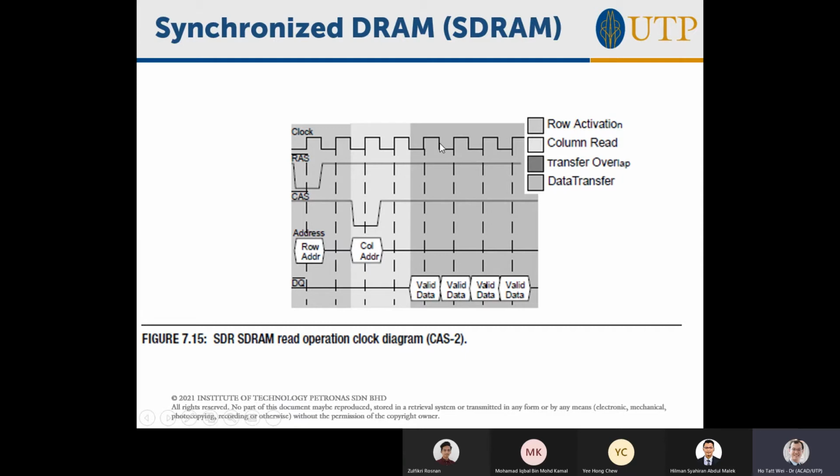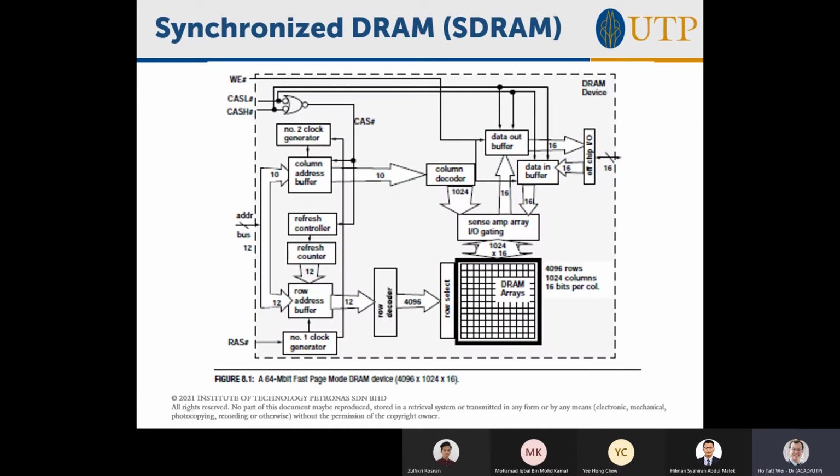That's the key difference. So DDR RAM is quite similar to synchronous DRAM. It's using the same concepts, except that the data is being sent out at both clock edges. So you get the first bit on the positive edge, the second bit on the negative edge, the third bit on the positive edge, the fourth bit on the negative edge. So it's faster. That's the main one. And I want you to recognize that this data output pin is called the DQ pin.